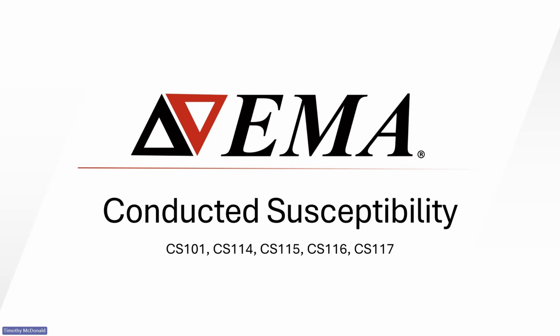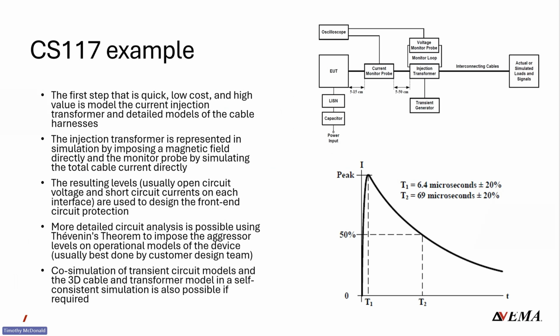CS115 is crosstalk from high power switching transients on maybe vehicles or industrial equipment. CS116 looks like an electromagnetic pulse that may be from a nuclear event or man-made type of pulse. And then CS117 is a lightning-induced transient response. So either an external stimulus or just power line coupling.